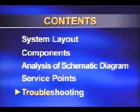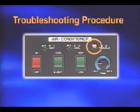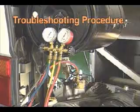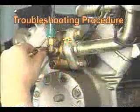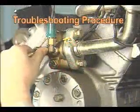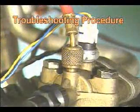At last, we would like to explain troubleshooting and common problem types of the roof-on air conditioning system. When the warning lamp turns on, or the customer complains about cooling performance, diagnose the problem by using a manifold gauge. The checking procedures are as follows. Install the manifold gauge to the low pressure line service port and high pressure line service port.